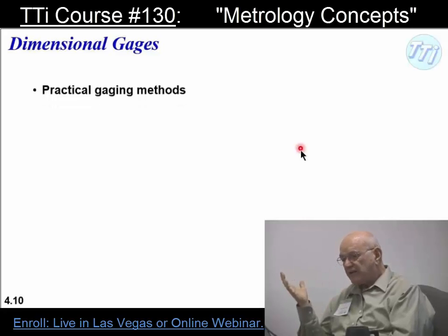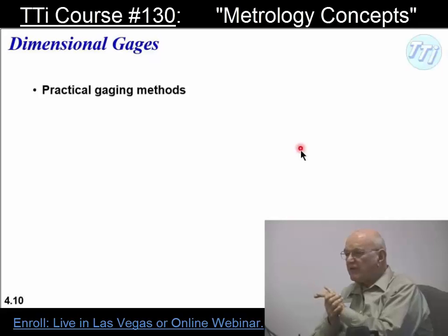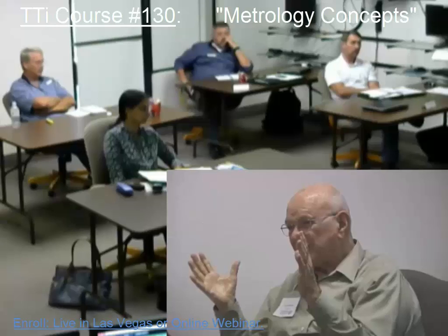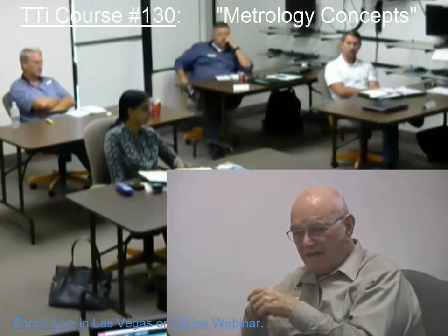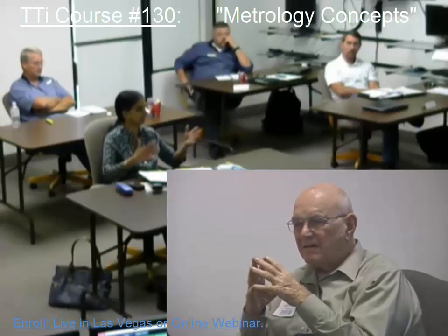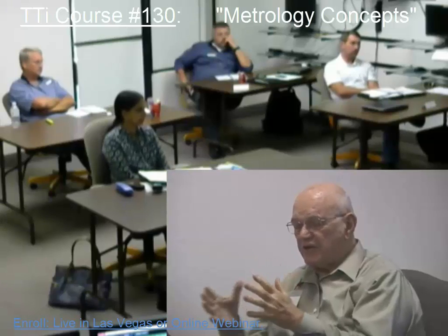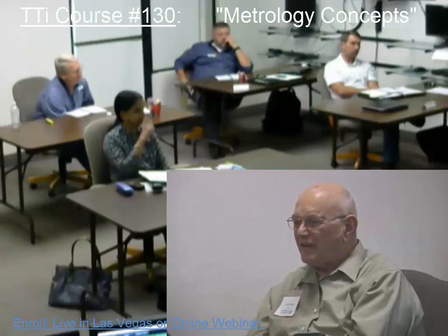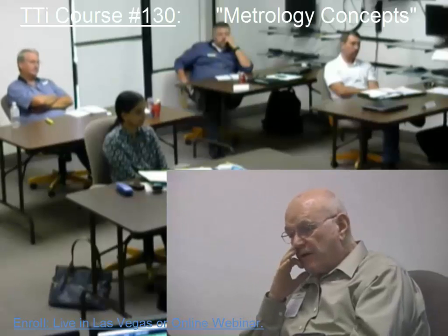Dimensional gauges, practical gauging methods. Anybody ever worked with dimensional gauges? What are some of the problems that you had with the dimensional gauges? Well, temperature. Always temperature, isn't it? And dimensional pin gauges have limits; they have to be maintained. You have to check them quite a bit, don't you? But some people say, gee, this is not anything electrical, I don't need to check that very often. You need to do it. And also temperature and cleanliness. Cleanliness, that's a very good issue right there.